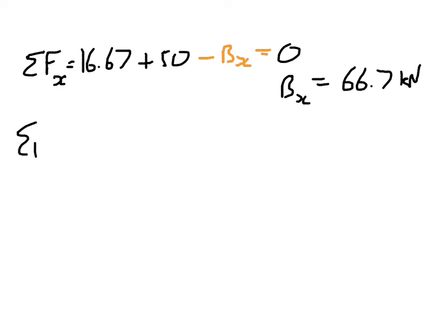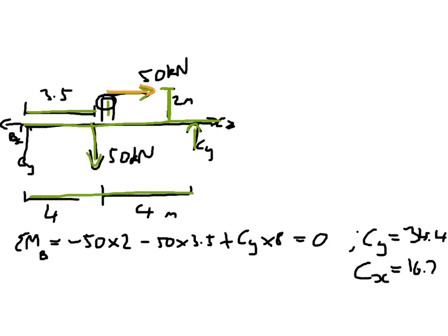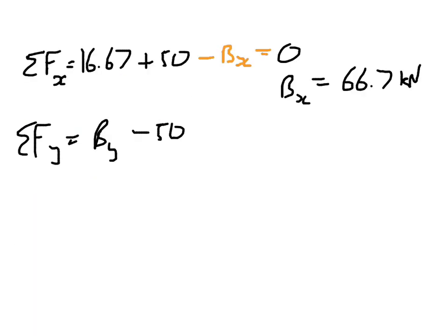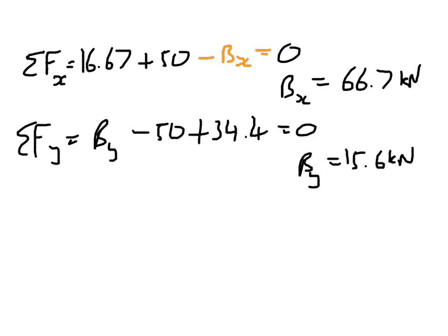And the sum of the forces in the y direction is going to equal BY minus 50, and that minus 50 is that part, plus 34.4, and that's your CY, and that all equals 0. So BY is going to be 15.6 kilonewtons.